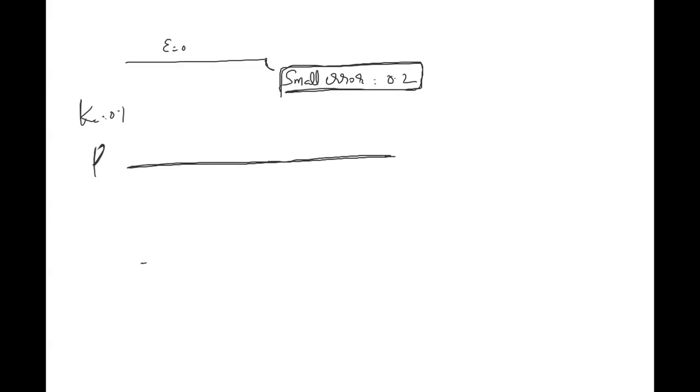With the PD controller, even if the error fluctuates a little bit, it jumps up the pressure, because under the assumption that pressure is going to increase in the future. Suppose it is really increasing, then it is a problem. Clear? If it is really increasing, it is a problem. But in reality, it is a small deviation because of some changes. So that is why this is not good.